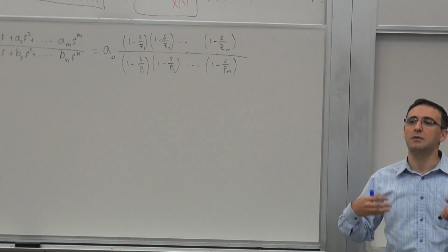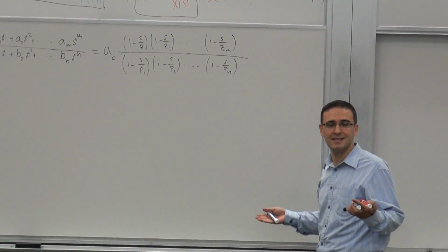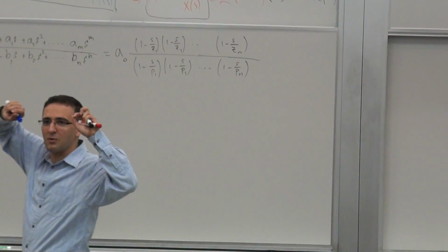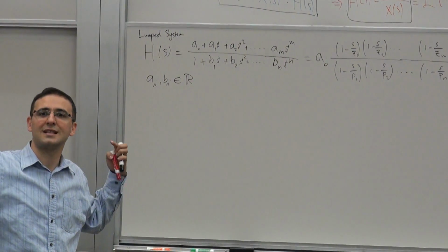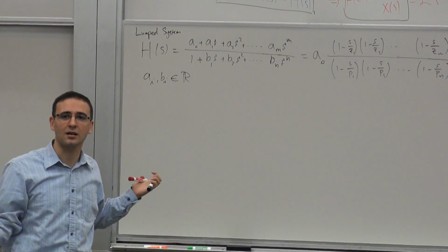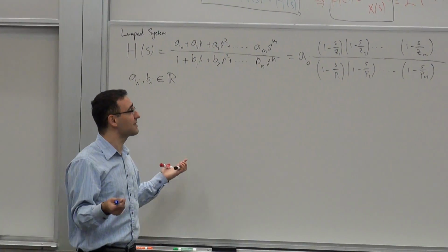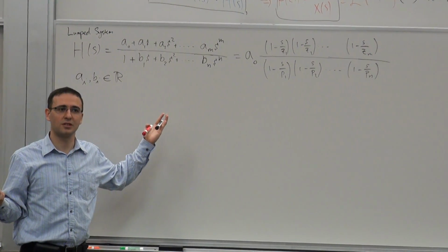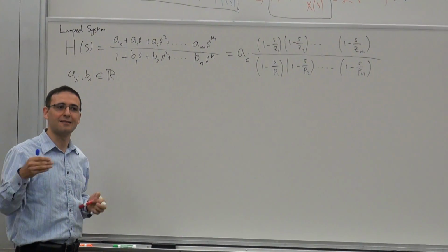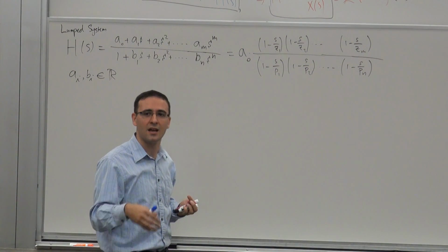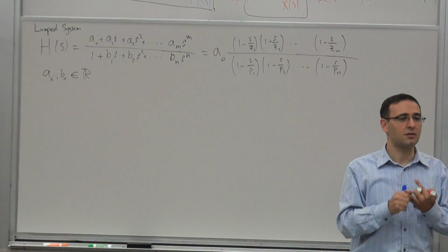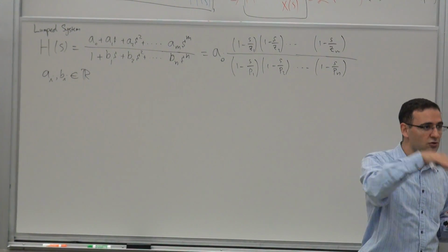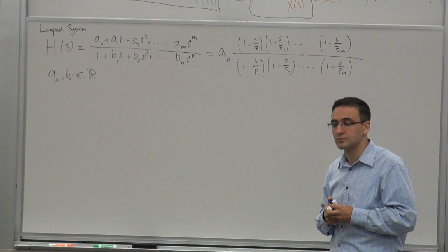But for a lot of things that we model, the way we model them, since they don't capture the higher-order small capacitors or inductors that we have somewhere else that will eventually kill the gain, or where the model represents the failure of the model, we will see things that have an equal number of zeros and poles. But we'll keep in mind that there must be some practical physical thing coming in that we haven't modeled. Either our model is incomplete, or we simply have not modeled it, that will cause the gain to drop at high frequency. Quick question.